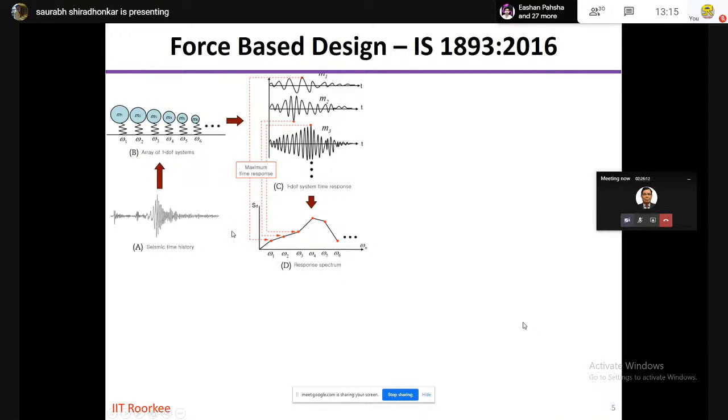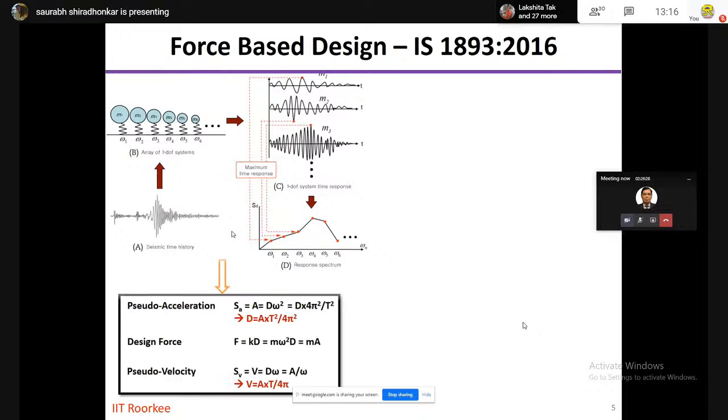Okay, now the funnier part is in case of earthquake engineering, even though we say we are designing for an earthquake, we are not sure about the characteristics of ground motion that are possible at a given site or at a building location. So to get rid of that, what we do is we do this analysis for various ground motions, and then we do the assemblage and figure out the design response spectrum.